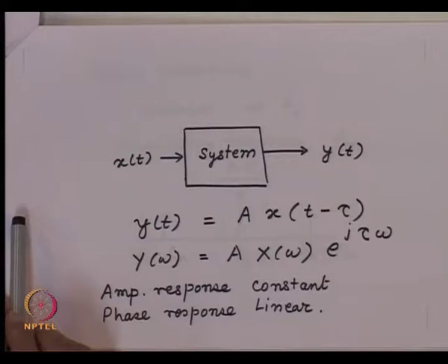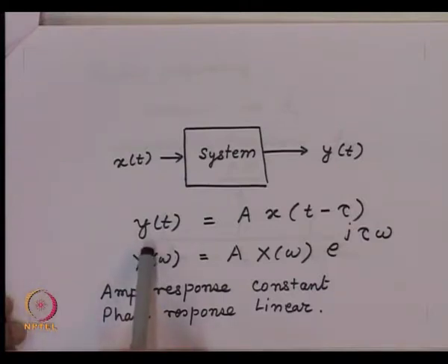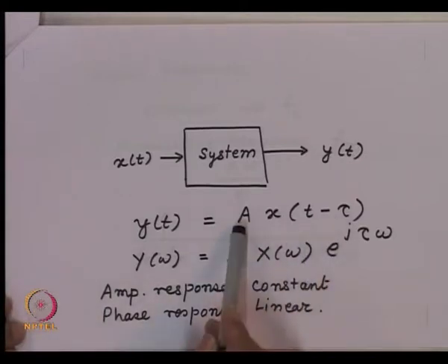And in the last lecture, we essentially introduced the concept of distortionless system. So, we said if you had a system to which the signal x(t) is applied, you get output y(t). Then we say signal is not distorted if y(t) is a replica of the input signal within a delay and with an amplitude factor.